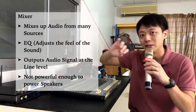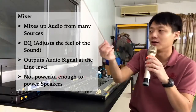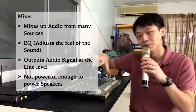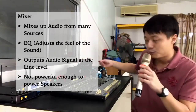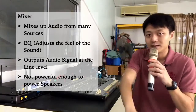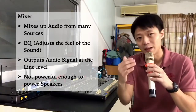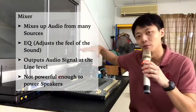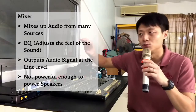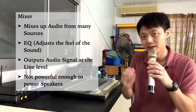It does some equalization. That means it adjusts the sound of each of these input sources, and then it mixes it up together, and then it lets you output this signal in line level only. That means it does not amplify your signal up to the speaker level. So the output from a mixer cannot be used to power the speakers because it is not powerful enough. It is just line level.